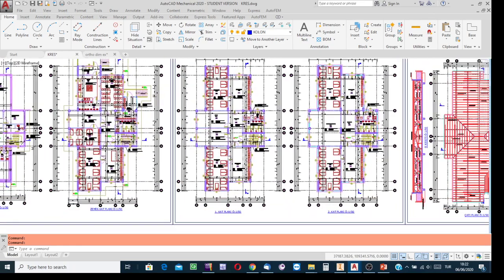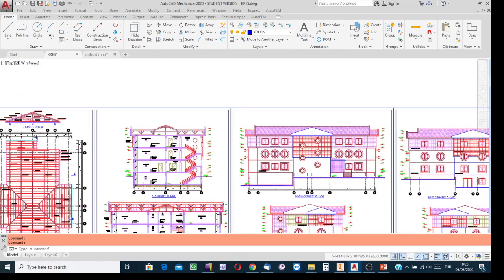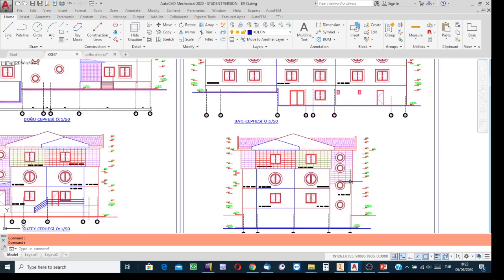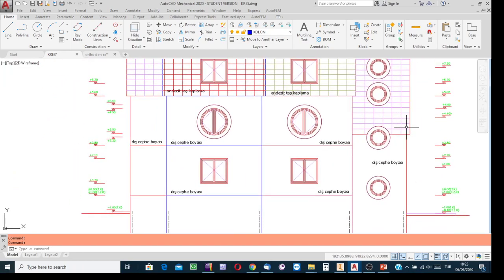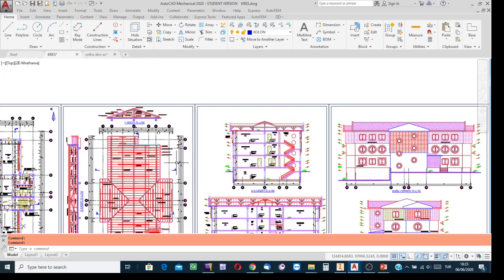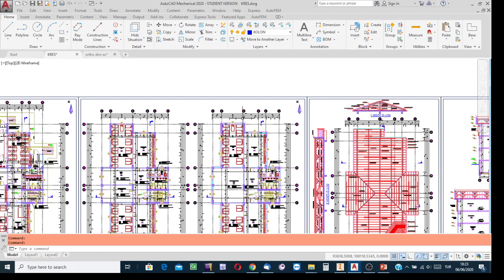Okay, well, this is the plan view. This is the east elevation. This is the west elevation. This is the south elevation. This is the north elevation. While looking at the elevation view, in theory, in general, say the front side view, the reader can see the altitude values. Looking at the plan views, the reader can see the delta x, delta y values. And then, it is in which shape? It's a rectangular prism. So in the mind, the reader can start visualizing the building three-dimensionally.